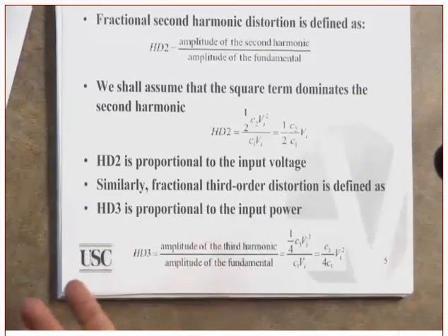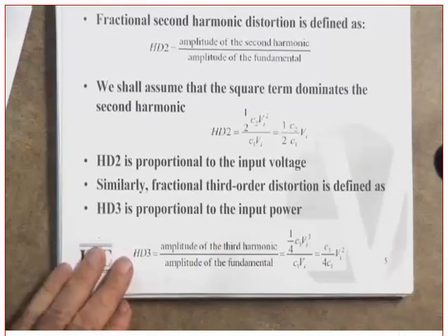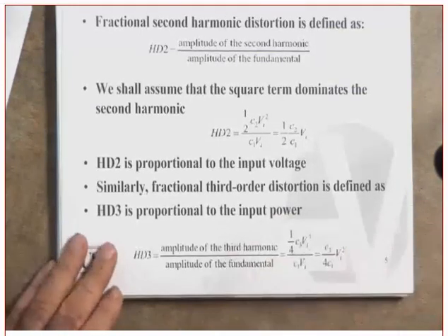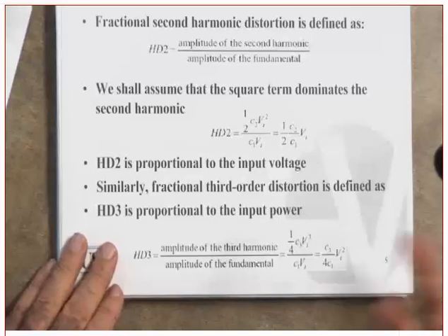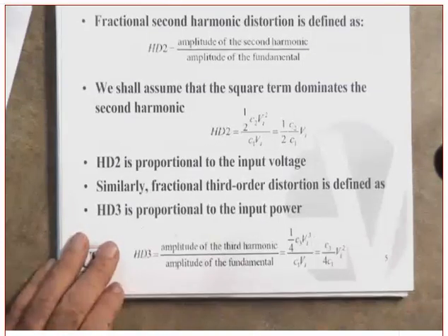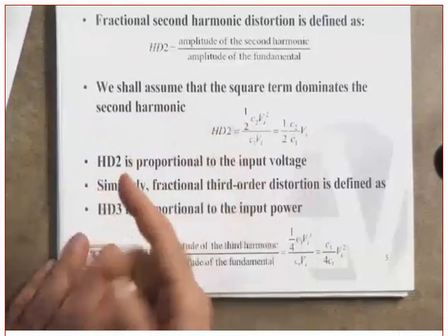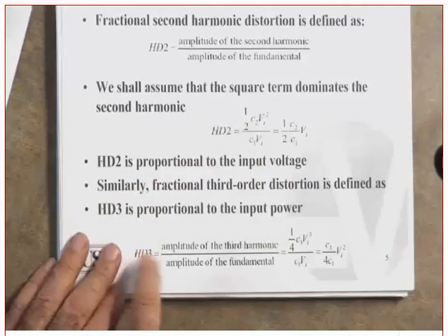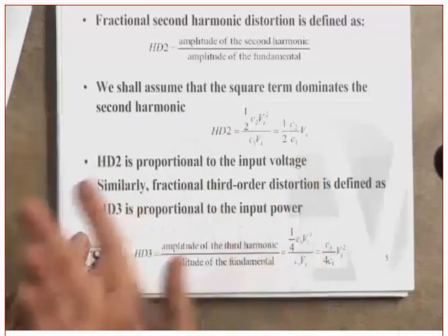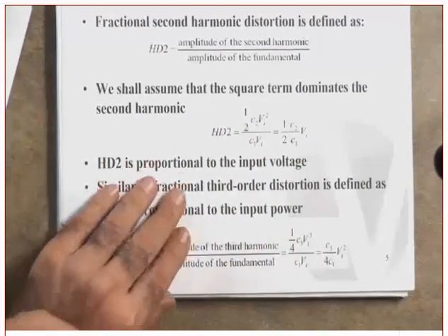That's, by the way, one of the reasons that you use power control. If the transmitter happens to be very close to the receiver, you really don't need to send that much power. Remember, the power is proportional to the amplitude square, which means you don't need to send that high an amplitude. If the amplitude is smaller, the effect on the harmonics will be a little bit lower. Clear? Okay, good.